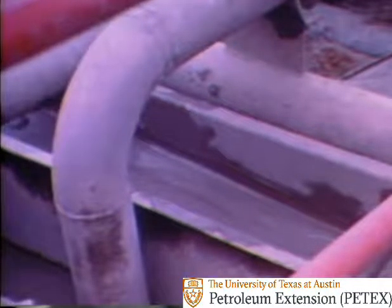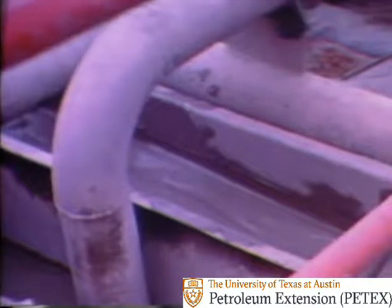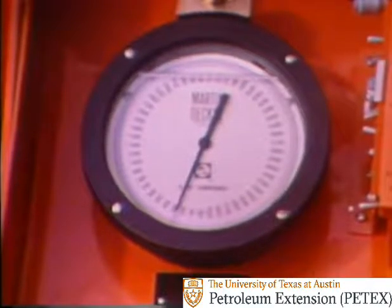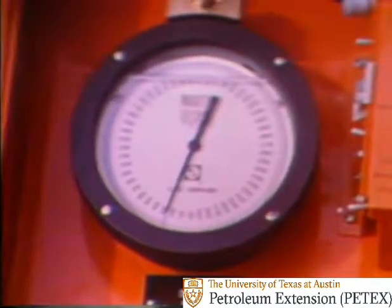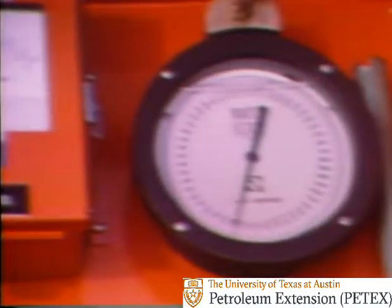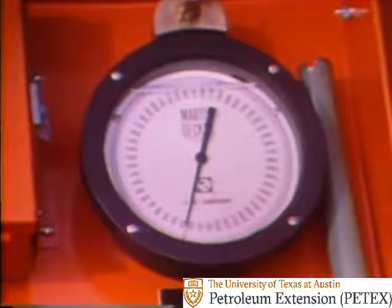When the intruded fluid has been circulated from the well, clean mud will appear at the casing outlet, and pumping can be stopped if desired, and both casing and drill pipe can be closed in. If this is done, you should find that both drill pipe and casing pressures are identical. If not, continue circulating.